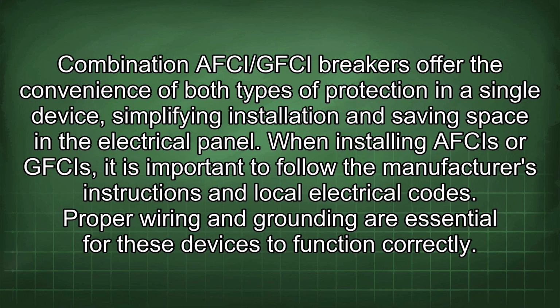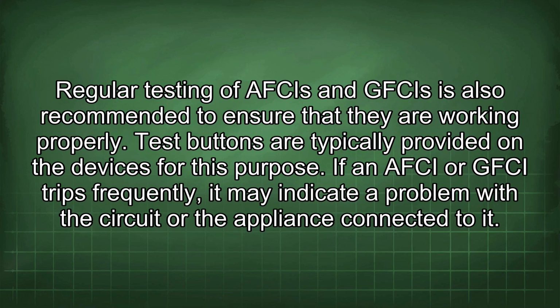When installing AFCIs or GFCIs, it is important to follow the manufacturer's instructions and local electrical codes. Proper wiring and grounding are essential for these devices to function correctly. Regular testing of AFCIs and GFCIs is also recommended to ensure that they are working properly. Test buttons are typically provided on the devices for this purpose.